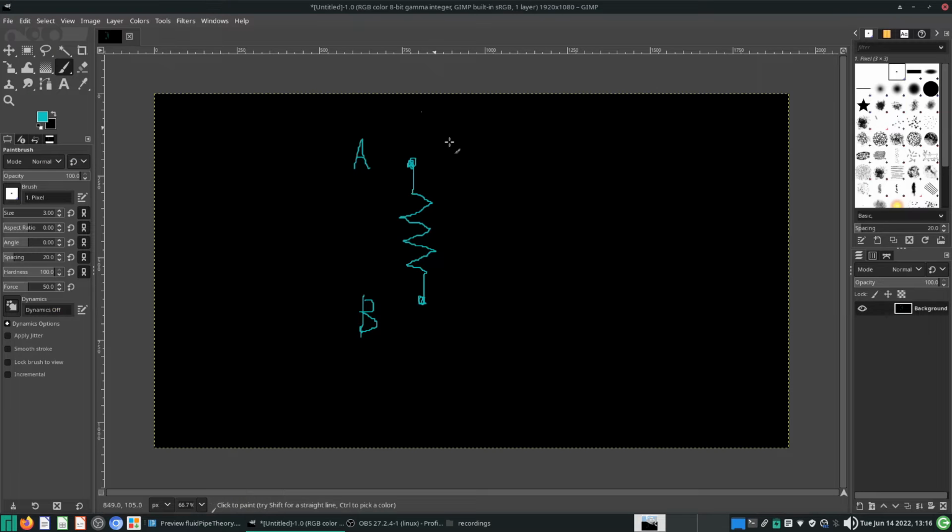Okay, so the current balance at A is called FA. So how do you do it? Well, the current balance is I out minus I in. So I out and I in should balance out. This should be equal to 0. FA is the current balance over A, and is the sum of currents out minus the sum of currents in. Just a reminder, the sum of currents out is by convention positive according to SpiceSharp.